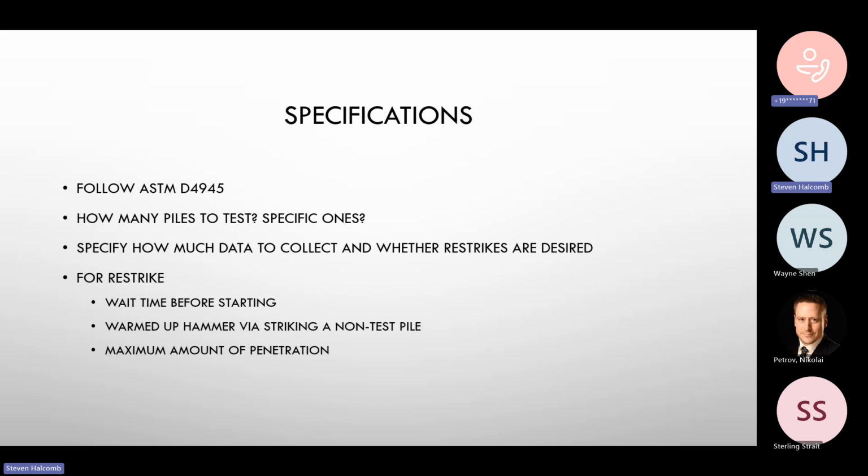The contractors try to be as minimal as possible, so they don't give a lot of extra room to drive that pile, and you're kind of down. I did one job in the Yellowstone where we had to send the sensors. Fortunately, we had an oversized corrugated pipe, but we sent the sensors about a foot down below grade because of the restrike distance we had to go.